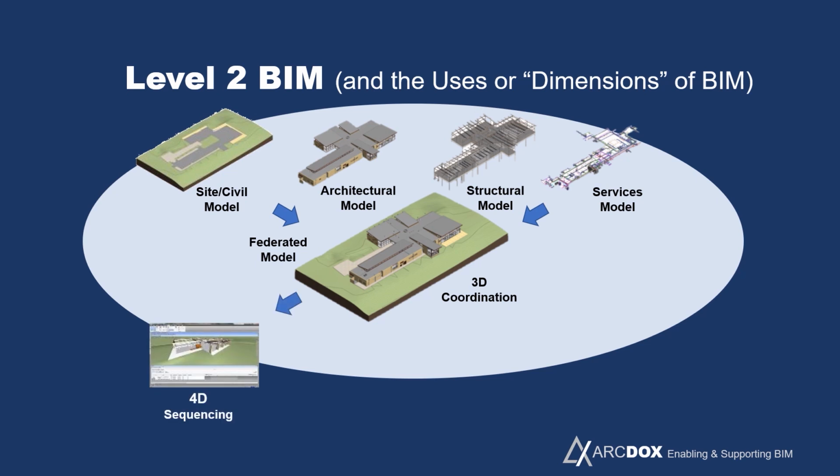But we can also do other things which we couldn't do before. So we can connect all these objects within these various models to the construction program and start looking at the sequence and the logistics. So what people are calling 4D BIM is really the fourth dimension being time connected to the objects. And in this environment, you can look at the sequence of construction. You can look at logistics such as delivery, site setup, temporary works, health and safety, fascinating things which were very difficult to do before.